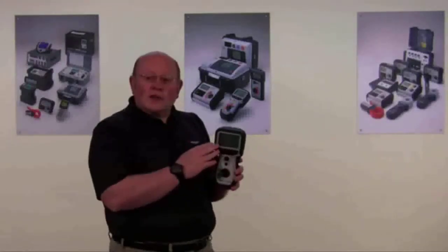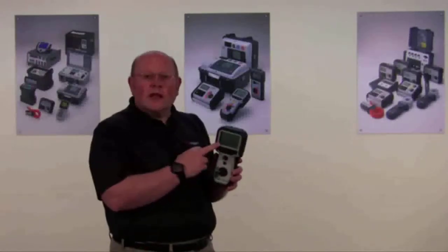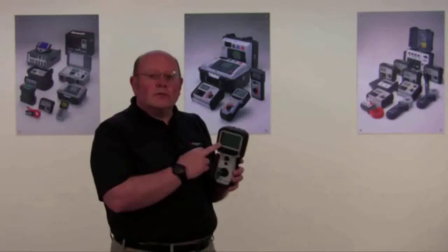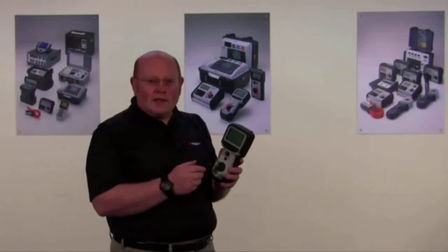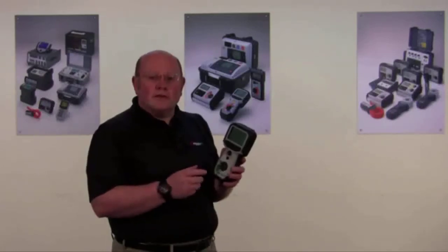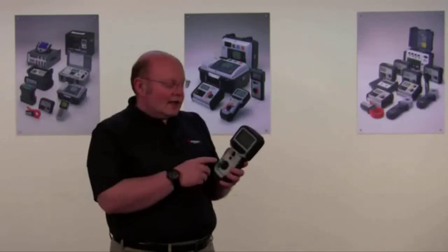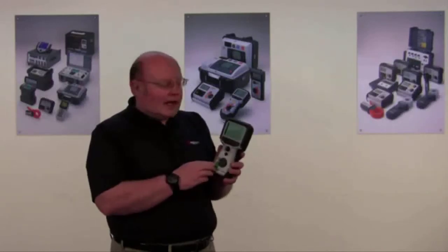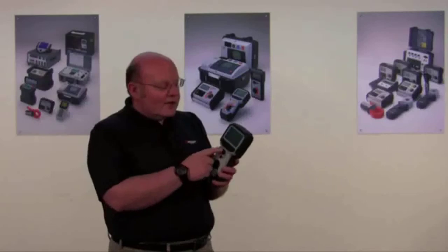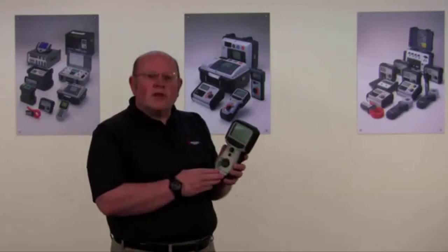It has a crystal clear backlit display, 4 times more resolution than a standard for this type of product. It has a very short pulse, 2 nanoseconds, to give you the ability to see those close-in faults. It's sealed to IP54. It has an auto feature. It has manual settings built in. It has dual cursors. It has a very simple 4-way switch for operation, and it's ideal for those simple jobs that you need to find a fault quickly.